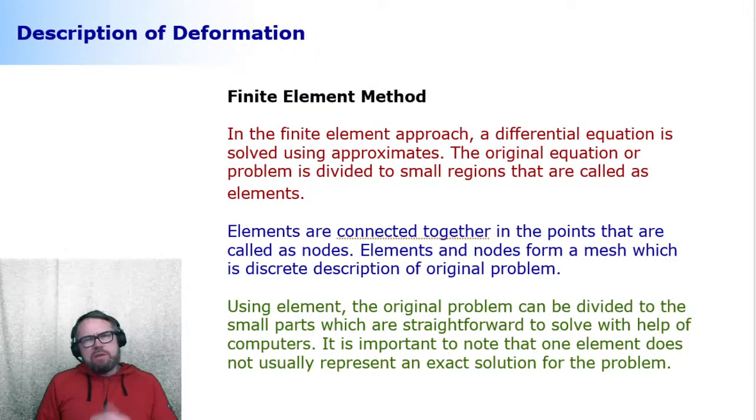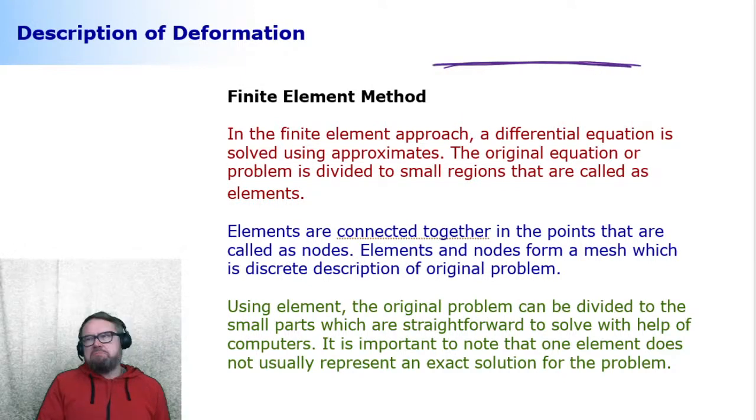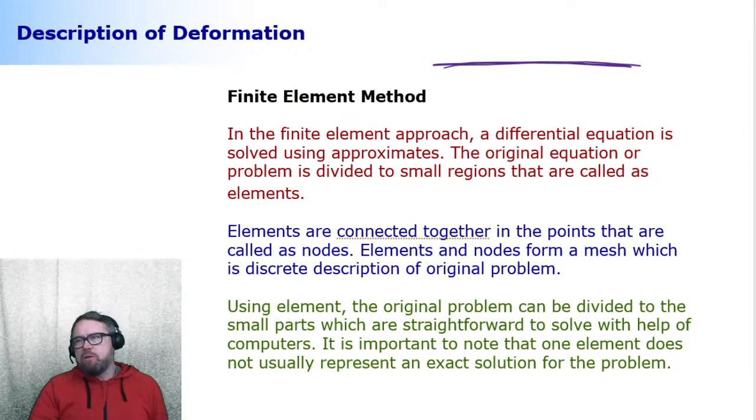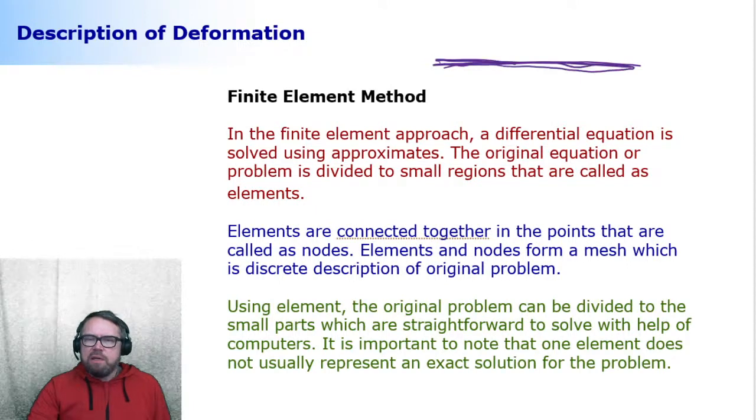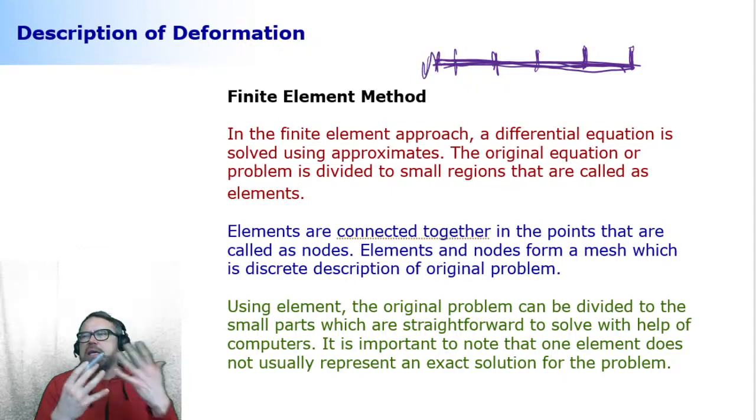But this is conceptually very different from multibody system dynamics, because in multibody system dynamics, if you have a beam-like body, that's your body. There's no need for any kind of discretization. In a planar case, you can describe it using 3 coordinates. That's it. But if this were a finite element structure, its deformation or flexible behavior can be estimated by using pieces of elements, pieces of structures that divide the structure into smaller pieces. The more pieces you have, the better solution you get. That's the nature of finite element modeling.